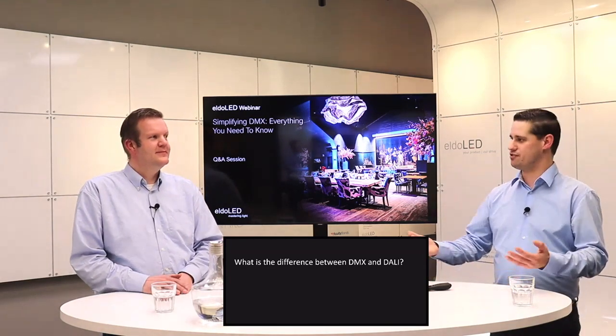There are 2 different types of protocols. One is designed for mainstream lighting, one is designed for architectural and entertainment lighting. So DMX tends to be more the entertainment industry, DALI tends to be more the general lighting applications. They both have their pros and cons. Is there a favorite? No, it's a matter of taste and application.